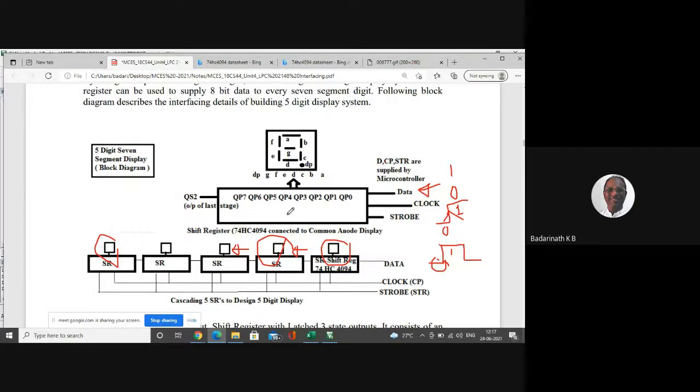The third component in the shift register is the tri-state buffer. In this configuration, the buffer is always enabled, so forget about the buffer. Whatever the output of the latch is comes directly to the pins. Whenever you push the data, bit by bit the data will be changing on the pins here. I don't want that effect to appear on the display.